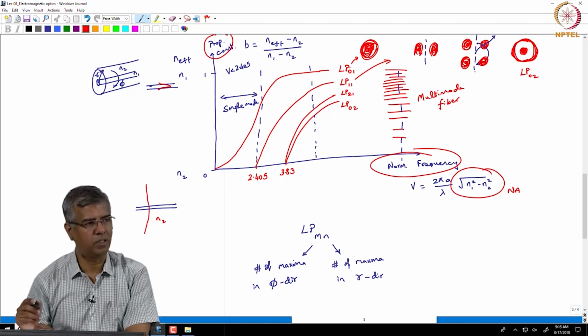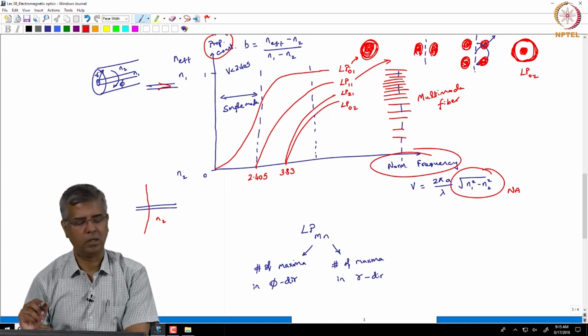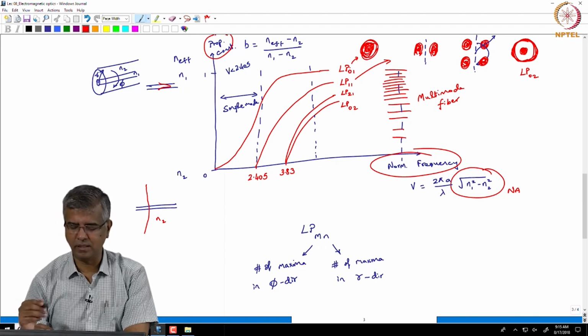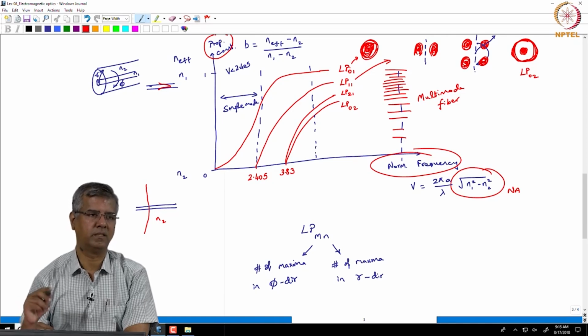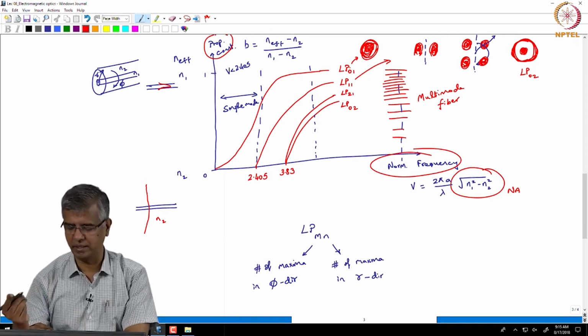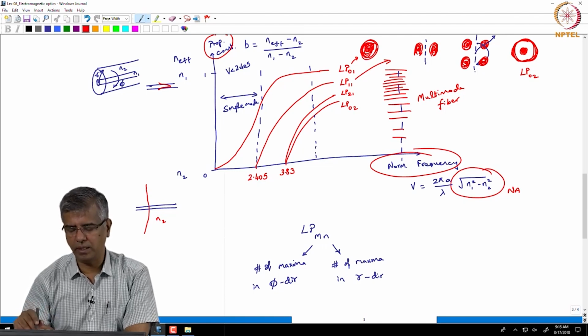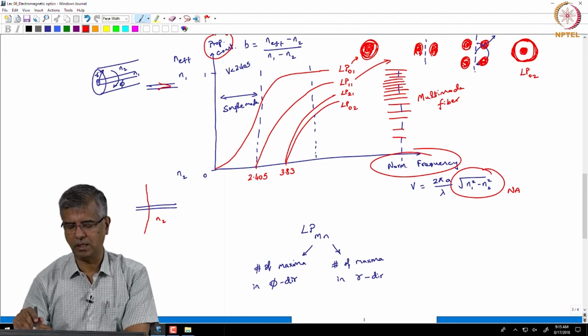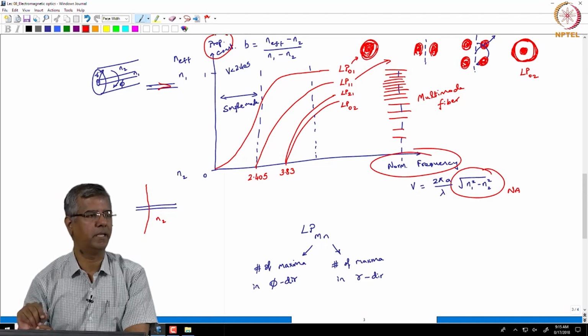There are two different configurations, technically called the HE11 mode. So, there is HE11 odd and HE11 even mode, which together constitute this LP mode. And when we look at the field configuration of this total LP mode, the electric field is actually polarized in a linear manner.